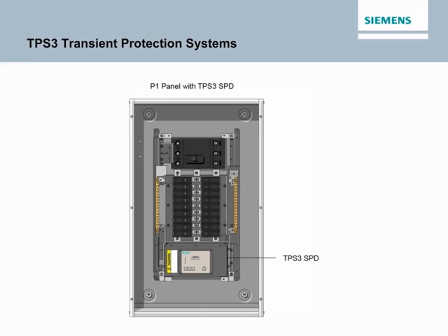Many electrical devices and systems are susceptible to damage from the high energy levels associated with electrical surges caused by lightning or other electrical equipment. Any component between the source of the surge and ground can be damaged. Therefore, electrical systems are at risk unless they incorporate surge protection. Surge protection is best accomplished by stopping surges before they get in through the application of hardwired surge protection devices, which are installed at key electrical system surge entry points.